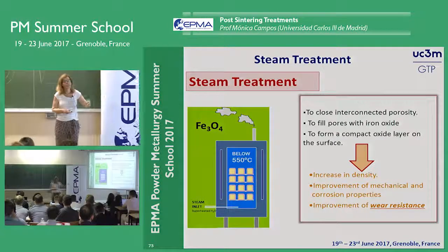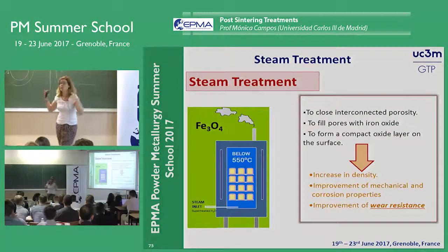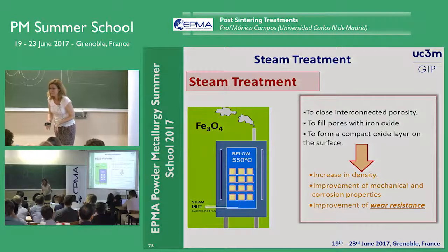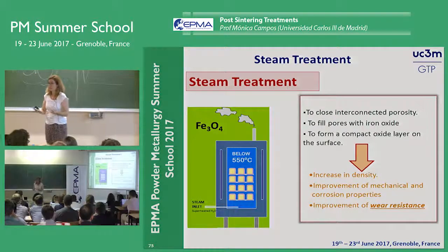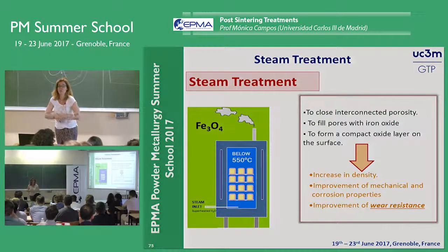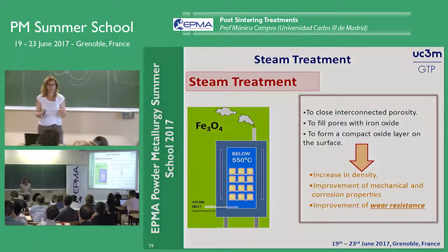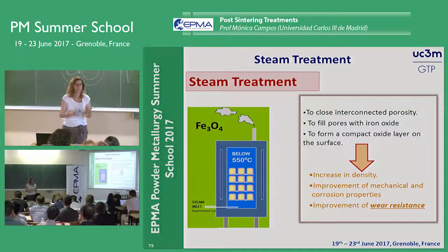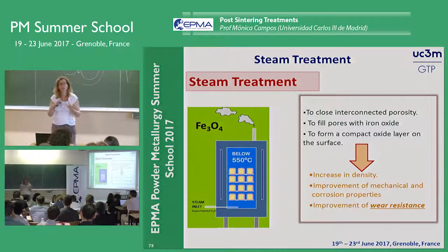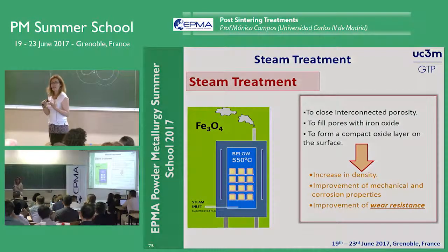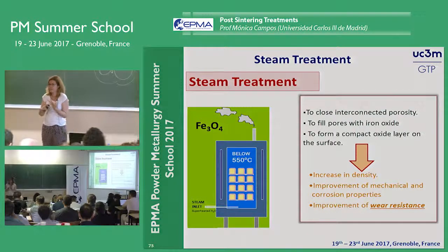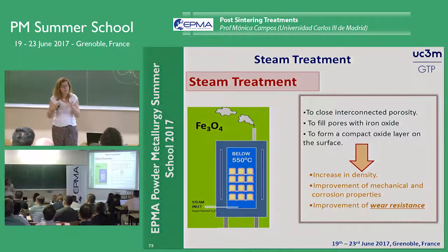Steam treatment is, I think, an old-fashioned treatment, but it works because it promotes an oxide layer that covers our surface perfectly. It works perfectly for wear resistance, does not decrease the resistance of the component, and can fill the open porosity.